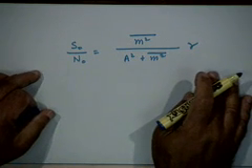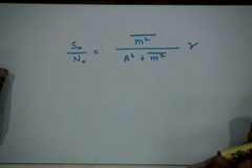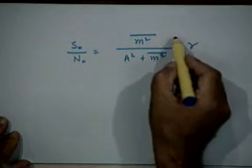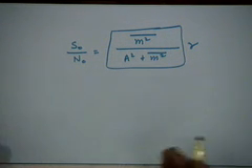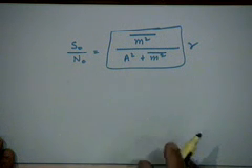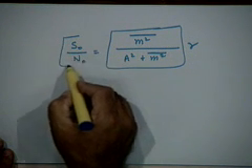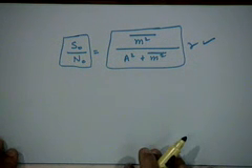This is DSB AM with some percentage modulation, an arbitrary modulation index, and we found that there is a reduction in SNR by this factor because of the inefficient use of the carrier, inefficient use of the transmitter power. But other than that, the output signal to noise ratio was linearly dependent on the input signal to noise ratio.